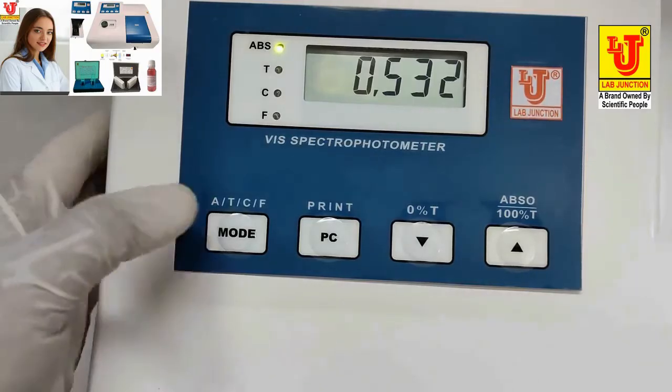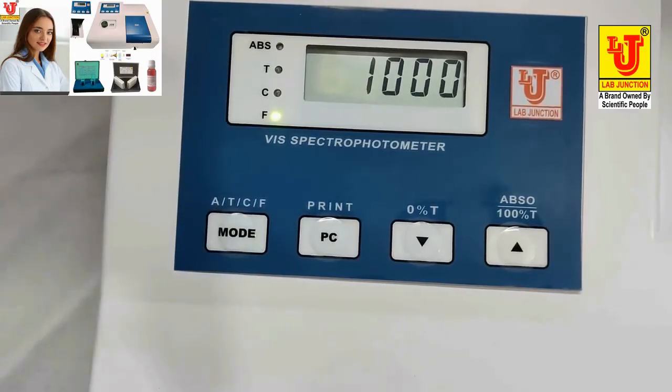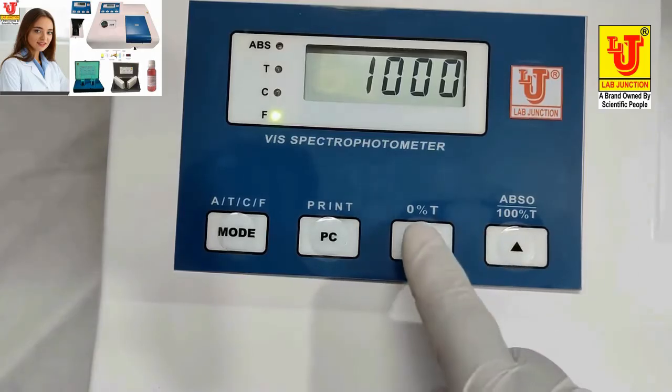For this, first you have to go to factor mode. Your standard solution value is 60 ppm. Then factor is equal to concentration of standard value divided by absorbance of standard value. That is, now if we calculate, that is 112. Then feed the value.